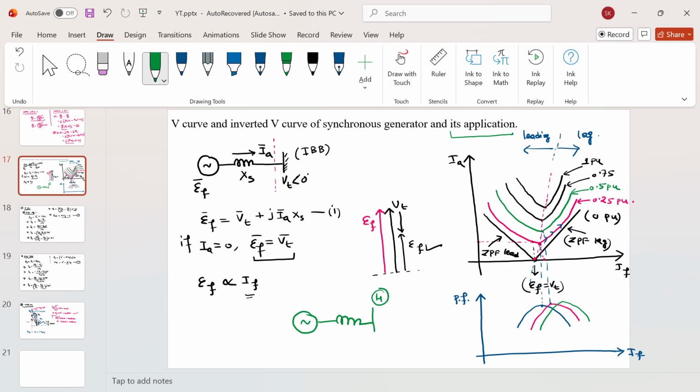Okay, it is a generator bus, PV bus. And after the load flow solution, you got to know that your generator needs to deliver some P amount of active power and Q amount of reactive power, and you will also get the bus voltage and the bus voltage angle. The load flow solution will give all of these things. What is the active power generation? What will be the reactive power generation for this particular generator?